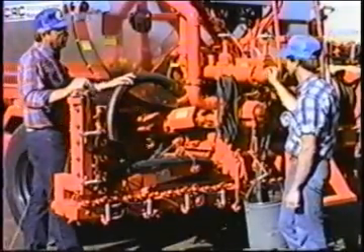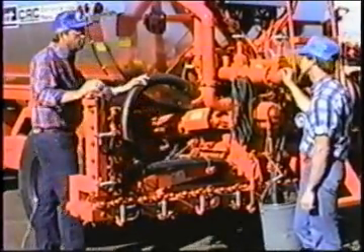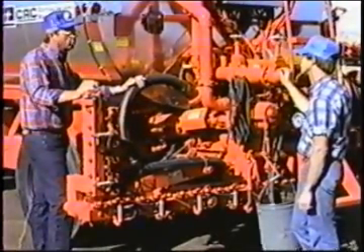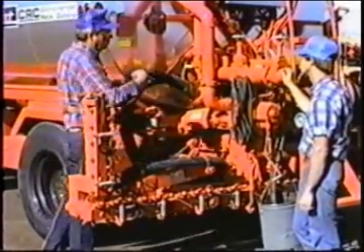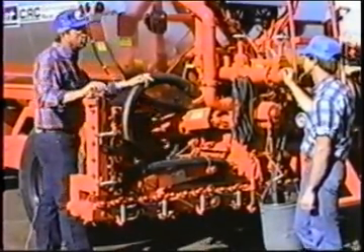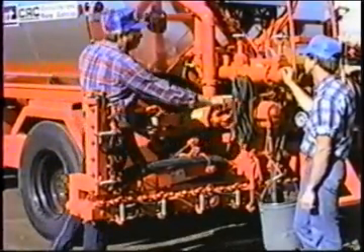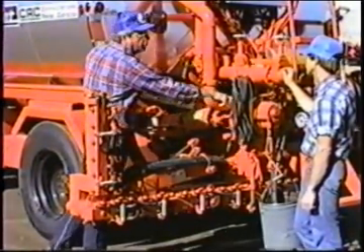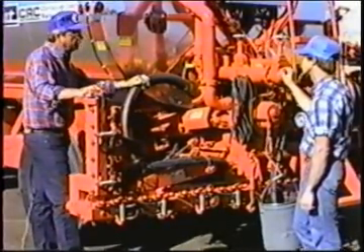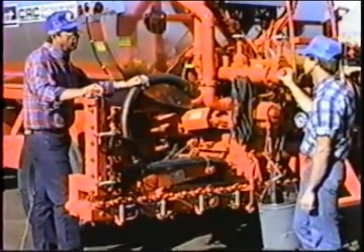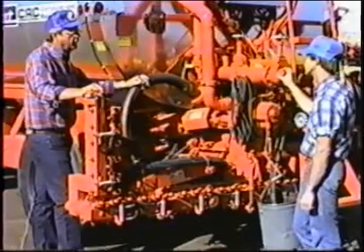This particular pump happens to pump 0.48 gallon per revolution, almost a half a gallon. That is, each time we turn the pump one full revolution, it moves 0.48 gallon from the bottom to the top if we're moving in the forward direction. So if we turn that pump at 10 revolutions a minute, it's going to move 4.8 gallons a minute.